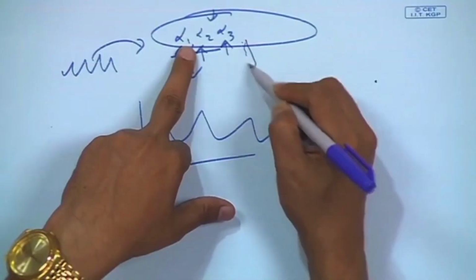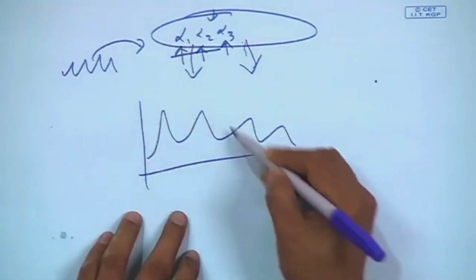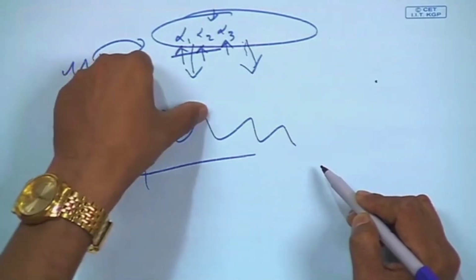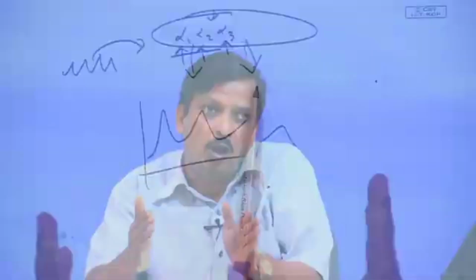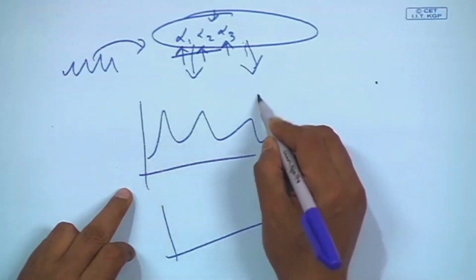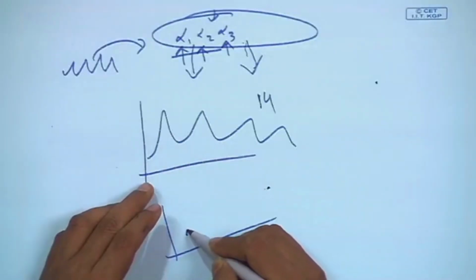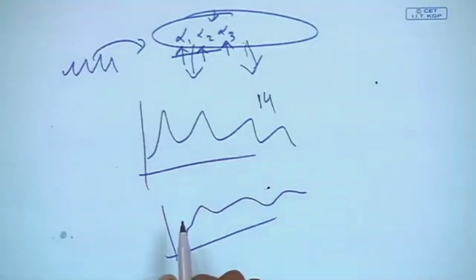Have you understood or not? So, if I say Fs by 2, number of poles, those coefficients represent the pole positions of the speech signal. Now, if I take the spectrum or the frequency analysis of these LPC coefficients, this should give the LPC spectrum, and it should represent the peaks at the formant frequencies. Now, if the order of the analysis is reduced, suppose I require 14 order, I make it 12 order. Then some of the formants will combine together and give me some broad kind of structures.